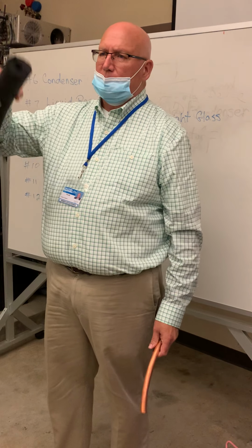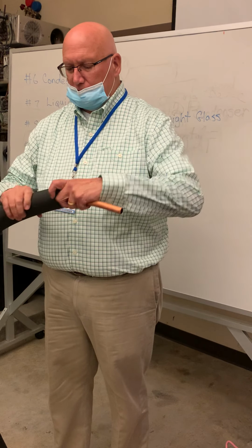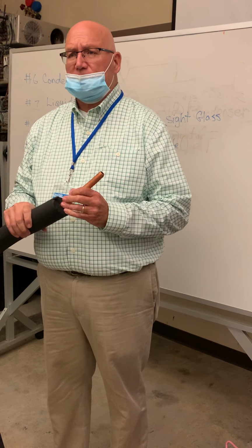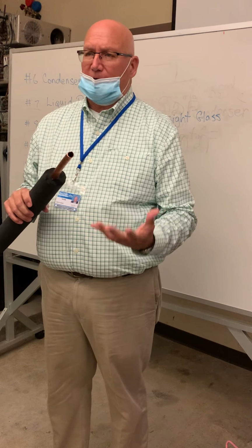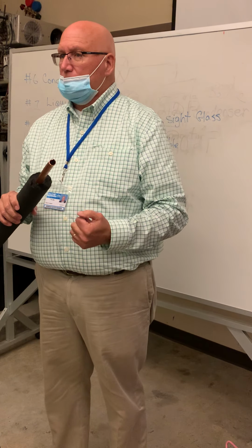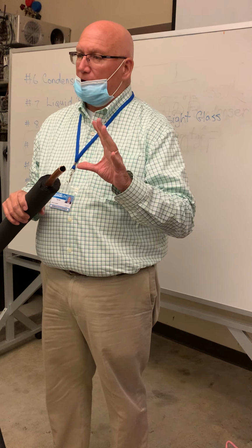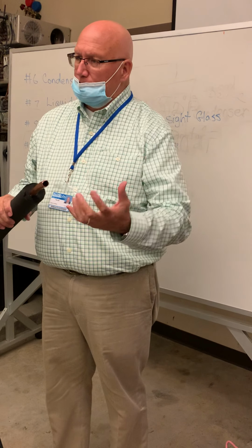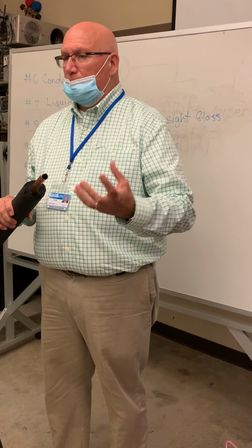The other thing about suction lines is they have to be insulated. He gets to wear a little coat. We want the suction line to be insulated because the suction line is what's being suctioned. It's the return line back to the compressor, and this is coming from the evaporator. So if the evaporator by design had liquid refrigerant at 40 degrees, it absorbed that heat until it became a superheated vapor.